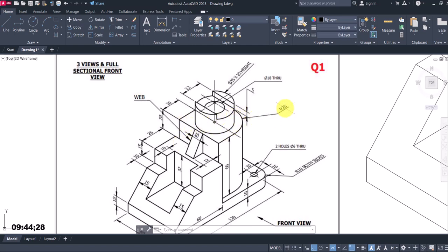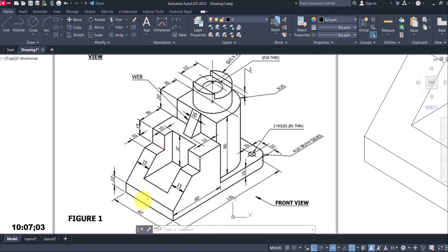Now I have a radius of 25 here. That is, for radius of 25, diameter of 50. So it means that from here to here is 50, the diameter from the back, the length of this line here is 50. I got that value from the diameter of the semicircle at the back. So from here to here is 50, and the entire length is 60. So 60 minus 50 is 10. So it means that there is an inward movement of 5 on both ends. So 5 here, then from here to here is 50, then another 5 to make everything 60.